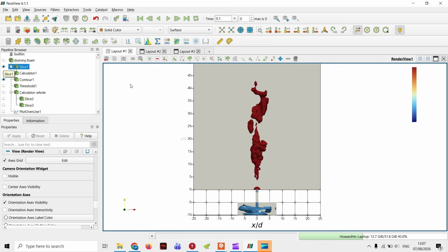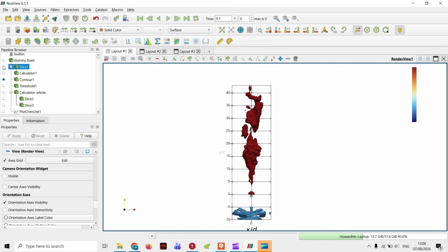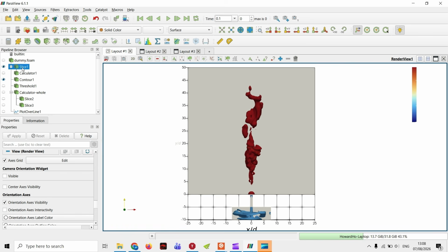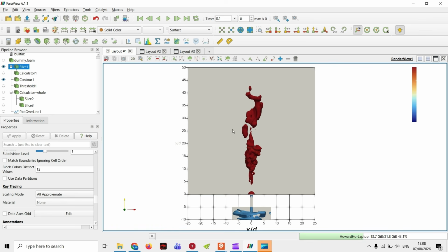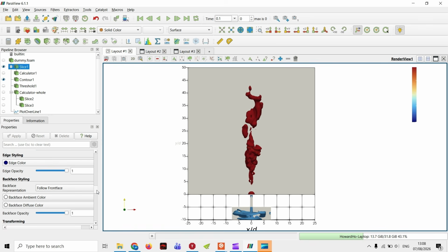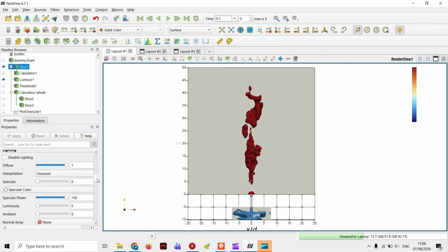Now we still have this kind of annoying background here. This is just our slice, but it's supposed to be white actually. The reason why it came out gray is under the lighting setting, the ambient. If you want it truly white, then you have to make it max to 1. But I usually use 0.4, even 0.2, just to give it a slight tint.